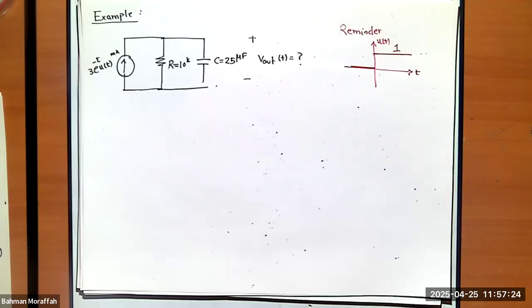That's the first point. Second point, look at this circuit. This is an RC circuit. So I can always write down the differential equation, write KCL on the top node, and try to solve the differential equation. Right? The forcing function is going to be exponential. So we're going to have to solve the first order circuit with exponential forcing function.